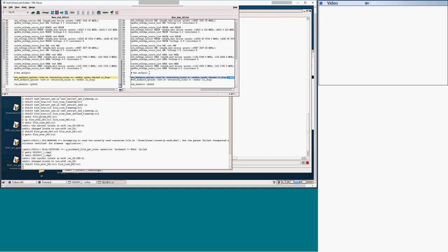But the difference in the results is really important, because for a static run, when you analyze temperature, for example, you get the saturated temperature. The tool calculates average power dissipation, and the temperature is the temperature that the circuit will reach over a period of time.